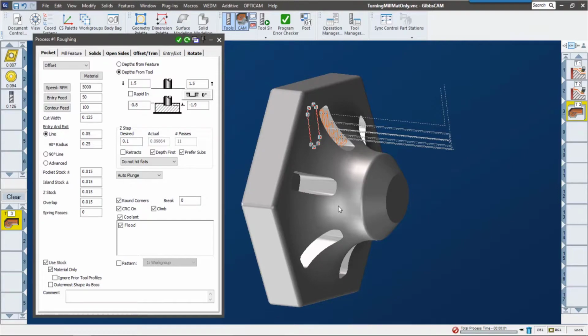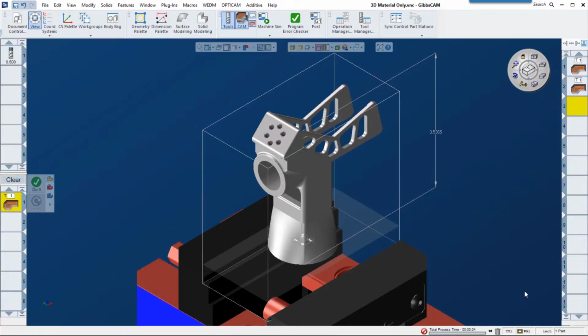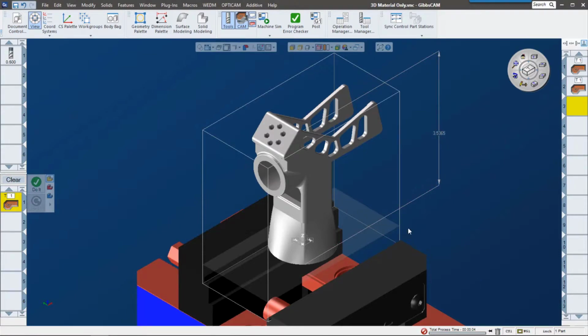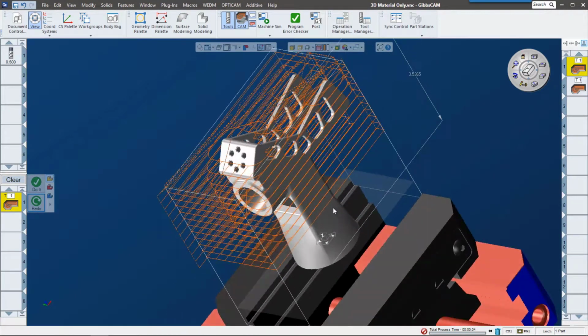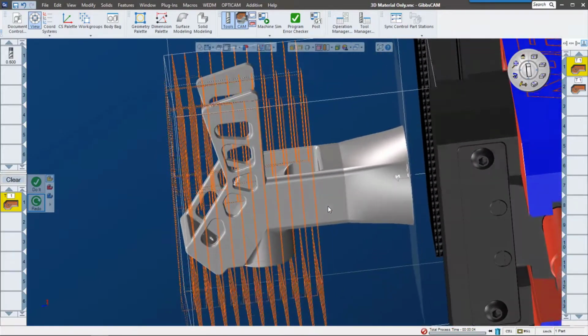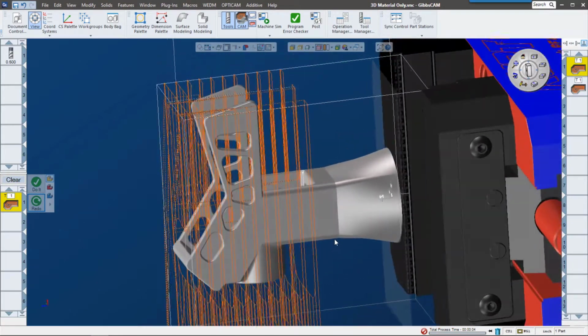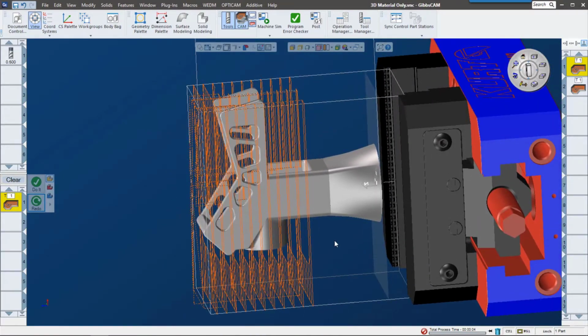Now let me show an example where it's between two milling operations but using different coordinate systems. This milling part, I want to machine on my 5th axis. I need to rough it out and finish it, but the reach on my roughing tool is only about 1.5 inches, and you can see here it's 3.5 inches tall. So I'm not going to be able to get all the way down. Now, the problem is I don't want to have my second tool in this setup have to go through and recut all of the material that it thinks is still there from the previous setup. And I'll show you an example of that with tool simulation.